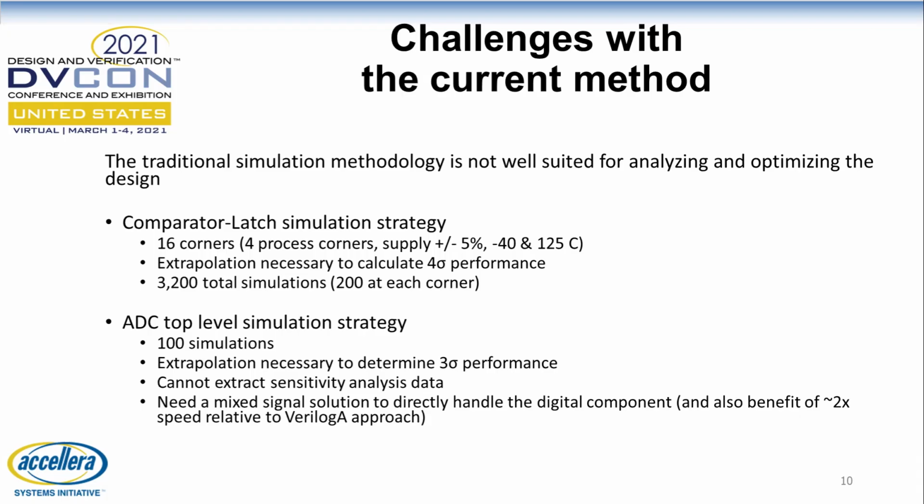Initially, the digital part of the ADC was modeled in Verilog-A. This simulates rather slowly and also does not verify the actual logic circuit that will go into the chip. Therefore, we switched to a mixed mode simulation so that we can run directly the RTL code of our digital team. So we were in need of a solution which can not only provide us with an efficient way of addressing statistical variation, but should work in a mixed signal verification flow.